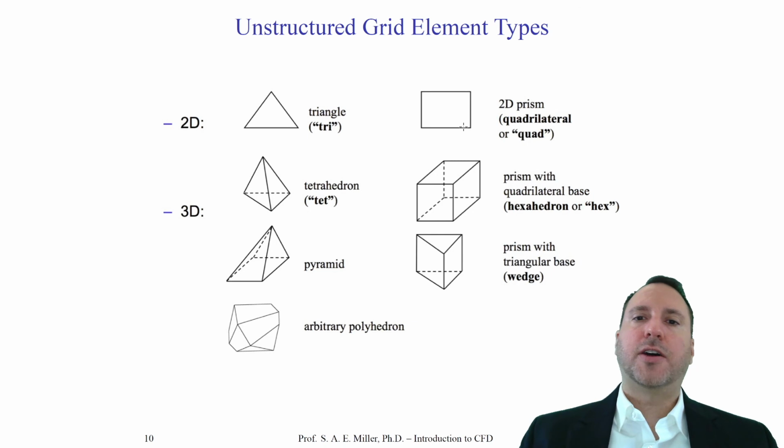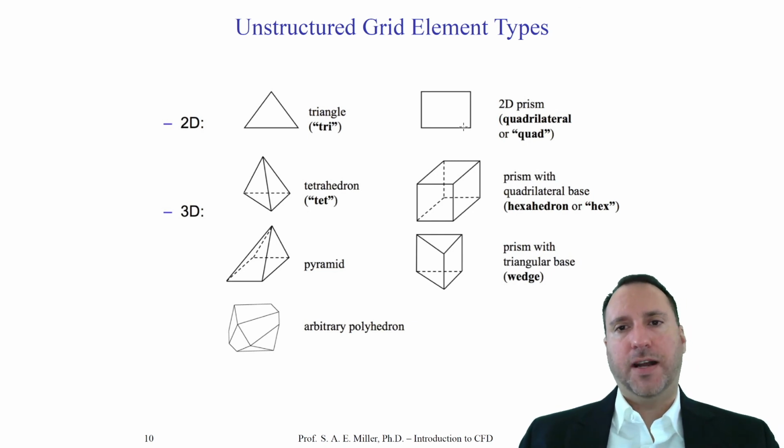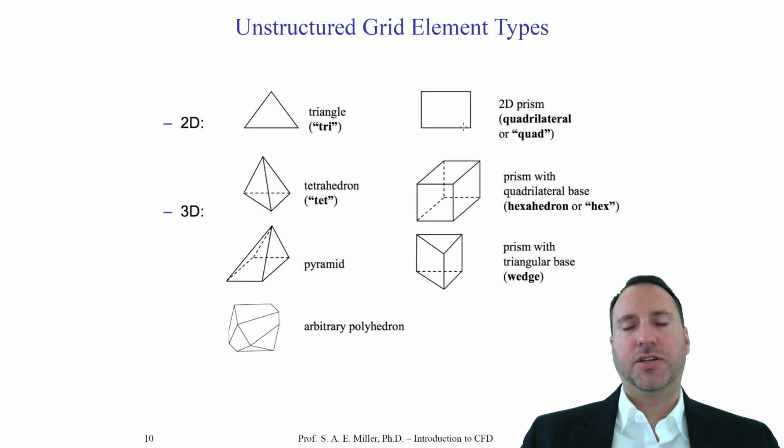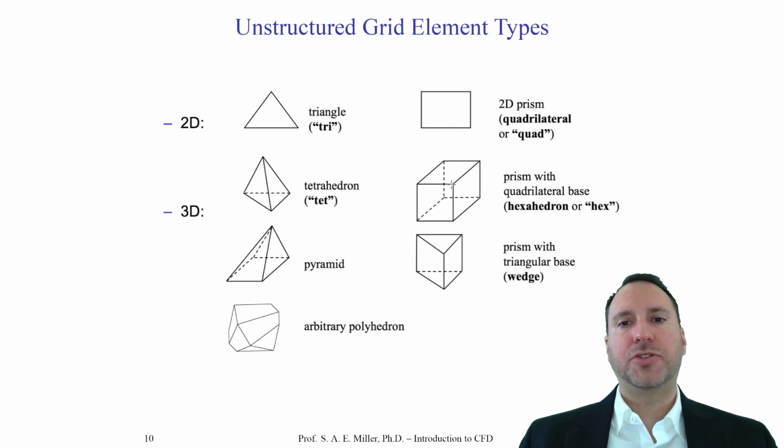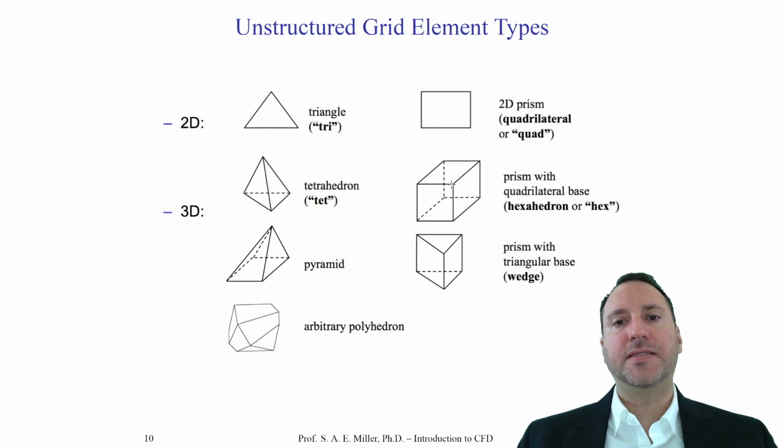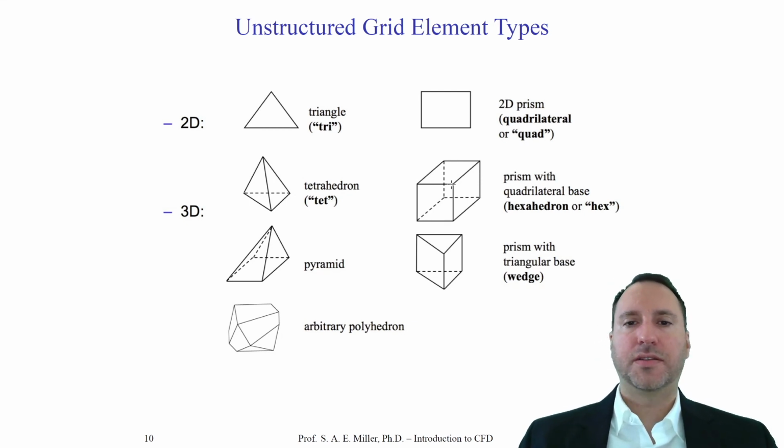You can also use an unstructured domain to try and find a structured mesh, and it might look like a bunch of 2-dimensional prisms or these hexahedrons. Now, it happens to be that these will still be unstructured meshes, and they would be incompatible with a structured solver. Remember, a structured solver will only read a list of nodes and not know anything about the particular connectivity, but it is implied to the solver.